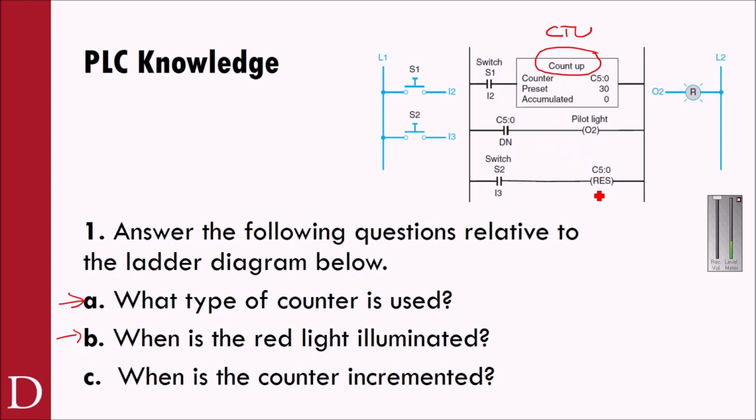So I want to go down and find, where's this red light? Well, here's this red light right here. What you'll notice as I look at this is everything in black from here to here appears to me to be the PLC code. If you look outside of the black, these would be your wired inputs, and on the right-hand side, these would be your wired outputs.